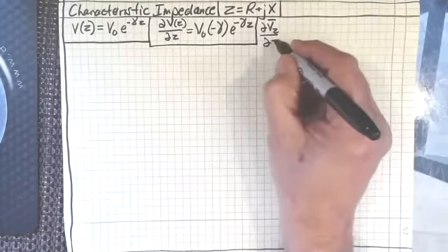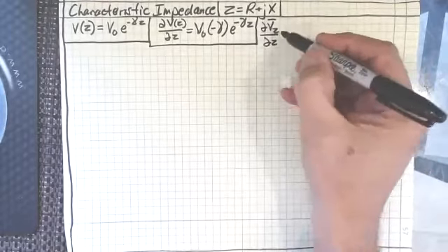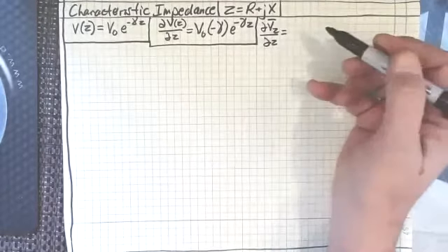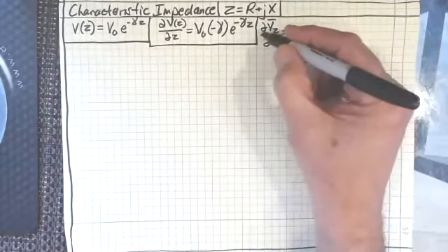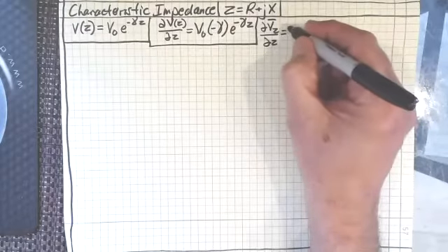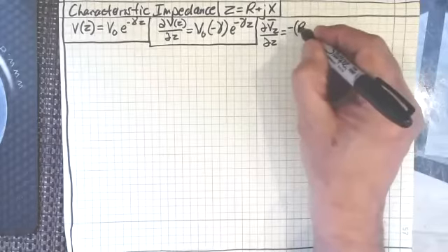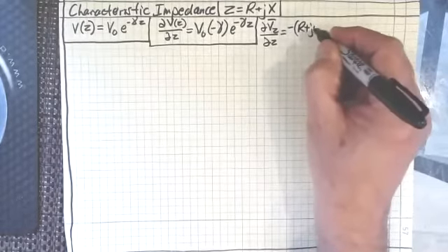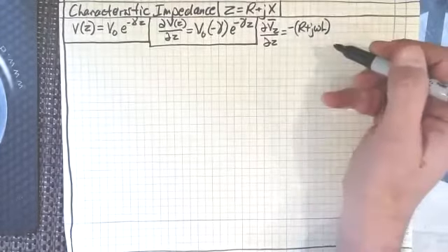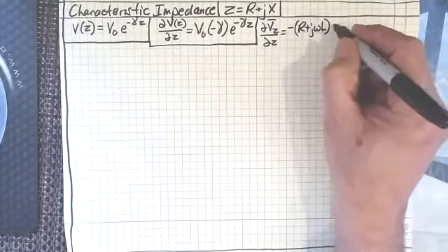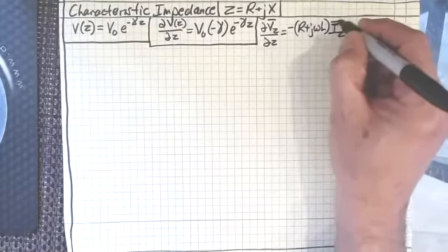Can't get enough of those telegrapher's equations, can we? Now, what I'm going to do is take the negative sign that I used before on the left-hand side of the equation and stick it over here on the right-hand side of the equation. That's all I'm doing. It's still going to be R plus j omega L, right, times I sub z bar.